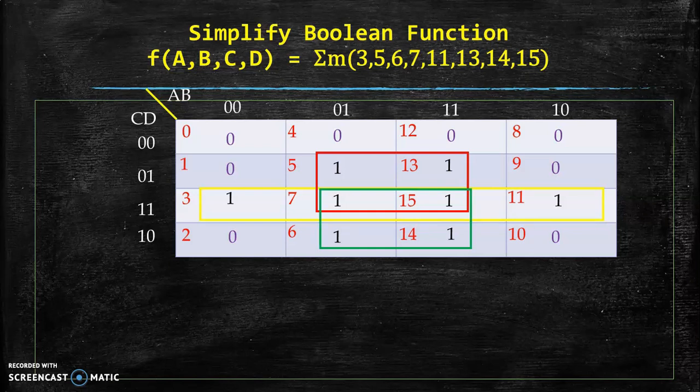So we have prepared 3 quads. Here we can see that there is no redundant group, right? If there is a redundancy, then we have to eliminate that group. The next step is to write a product term for each group. So we write a product term for the quad. In this we can see that it covers the entire row, meaning A and B both variables are eliminated.